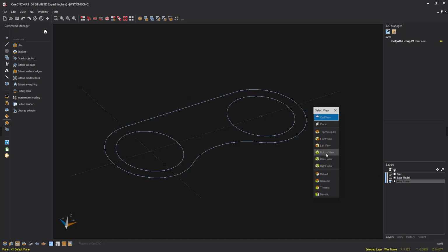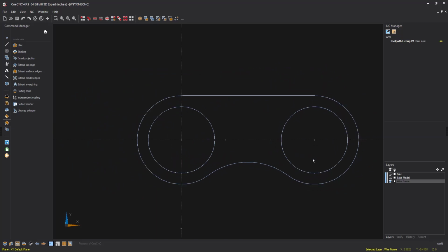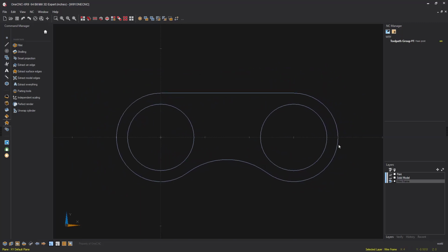And remember, the solid model is not required for toolpath. All right, this looks great. Why don't we start to apply our toolpath now? The next step really should be to create some stock. So why don't we do that? Though we don't need to create a separate layer, why don't we do this just for good housekeeping? So again, within the layer browser, we're going to right click, select add a layer, and that layer is going to be called layer 1. So I'm going to highlight that.